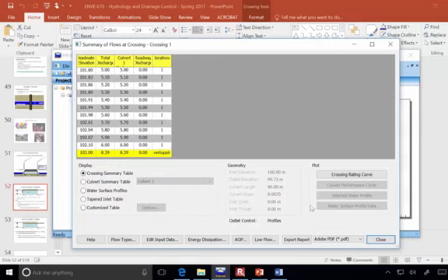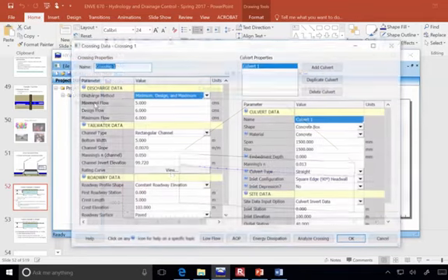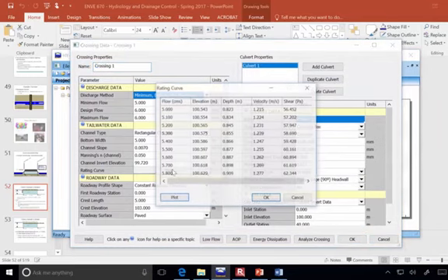Okay, so for 5.7, what is happening with the tailwater? So we can go here to the tailwater calculations. Here's this flow of 5.7. The depth downstream right now is just 0.898.